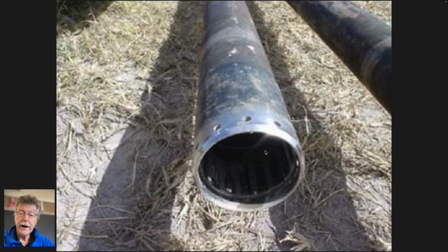This is the bottom of the core barrel, which sits inside the cutting bit. These little pieces inside may or may not be pieces of spring steel. So in other words, like a comb that you comb your hair with, these pieces of steel are there to catch the core, let it progress one way, but not let it fall out of the bottom when you detach this thing and pull it up the hole.